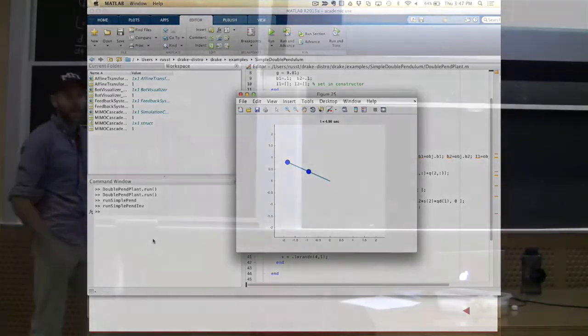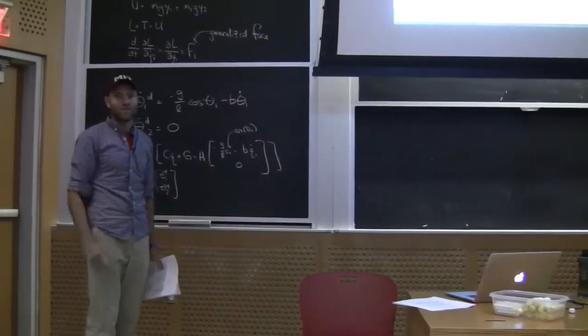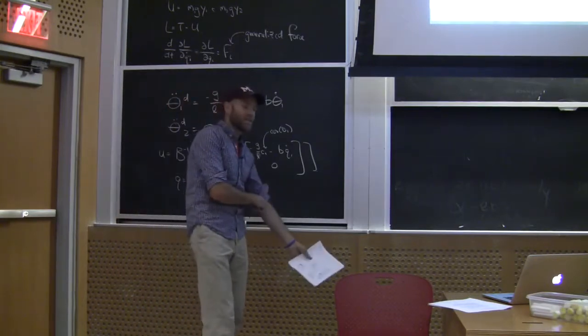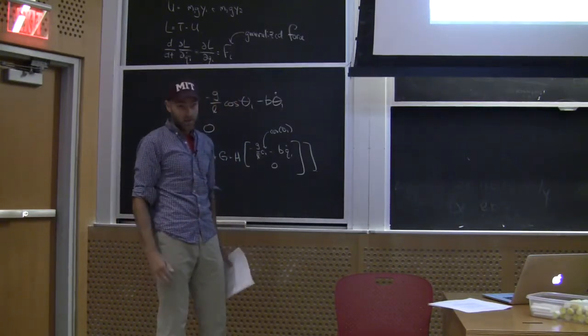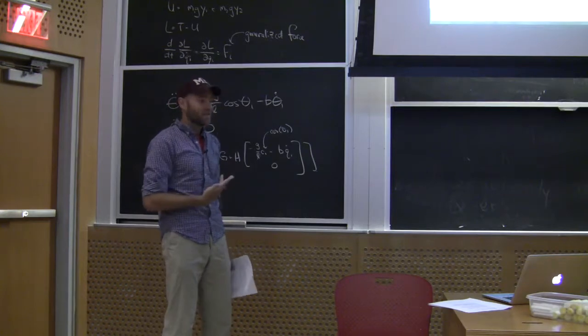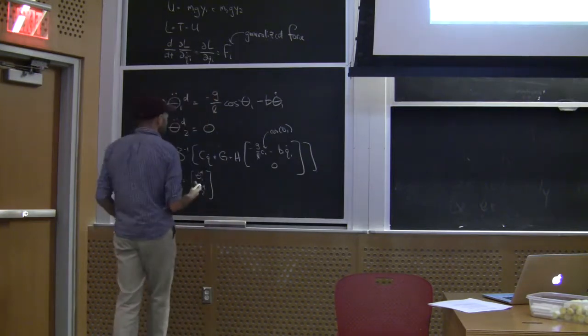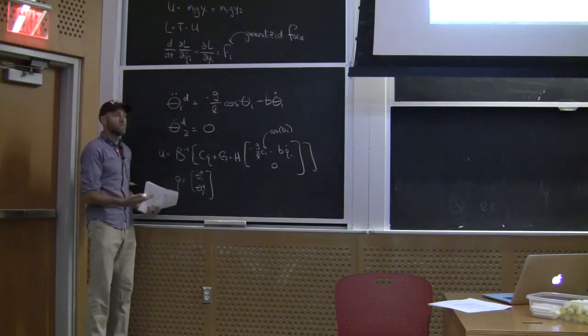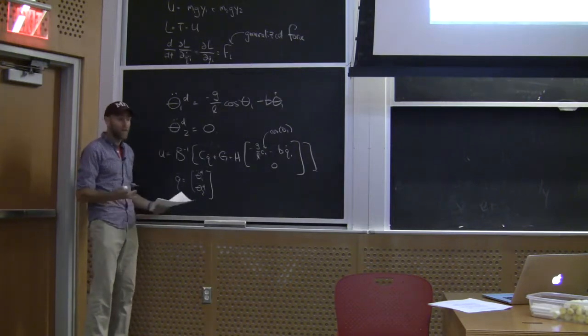Right? If I want to balance it at the top, well, just make it act like an upside down pendulum. That's no problem, right? That's easy. The math is easy, right? If I have torque limits, I can't do that, okay? But the math is easy, right? So feedback linearization is actually a beautiful, powerful thing to do, right? You should do that when you can.